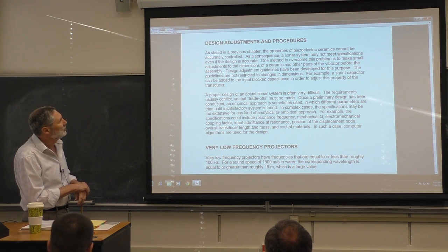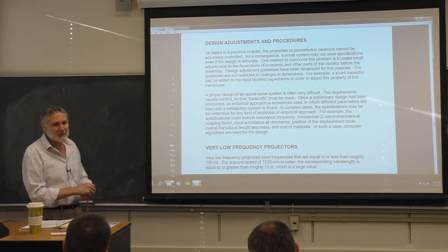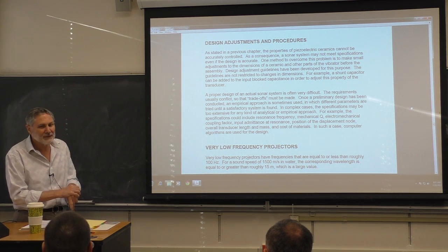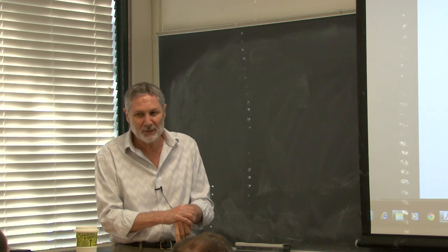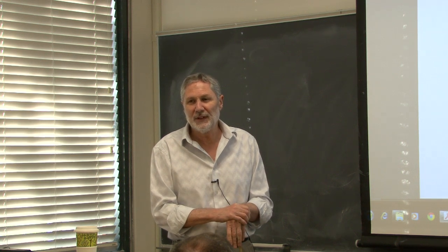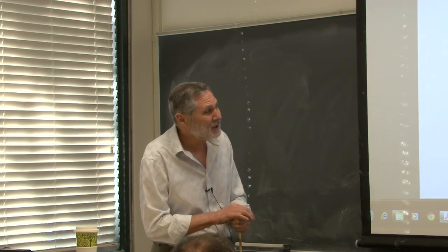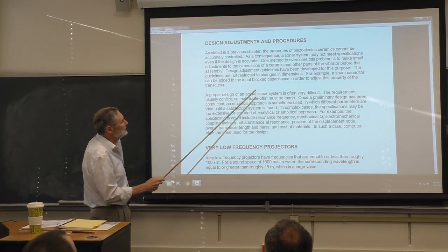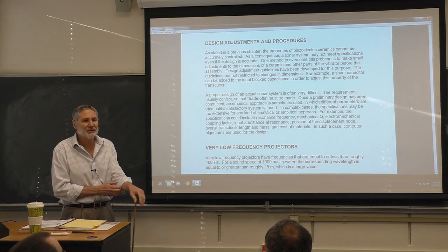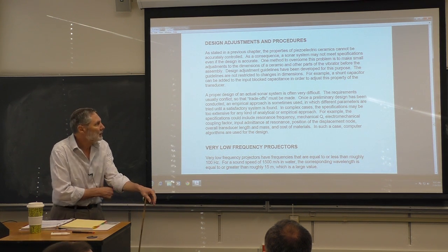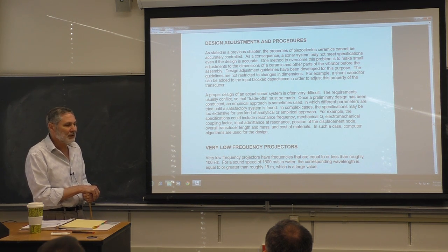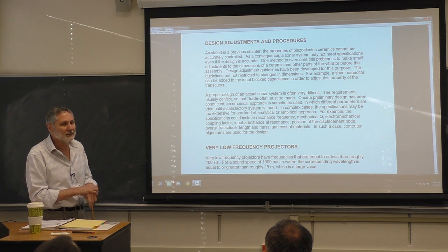But even one thing you need to realize, that even if you come up with the great, perfect design, and you have this thing, somebody makes this, you make it, or somebody makes it for you, it still could fail a requirement. And that's because the specs on piezoceramics is, uncertainty of roughly 10%. So that could cause trouble. Remember we discussed this before, that they just can't manufacture these things to very good precision.